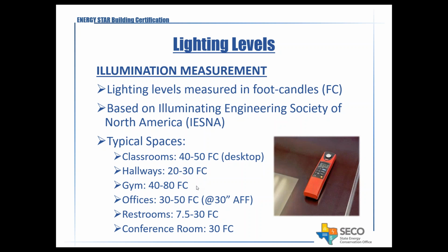Just note that UIL gyms in high schools will actually have a higher recommended foot candle level than, say, an elementary school gym. For offices, they're looking for 30 to 50 foot candles, and that's typically measured about 30 inches above the floor. And then restrooms, conference rooms. Different space types will have different recommended lighting levels, and that's what we're really looking for during the site visit. So typically we will spot check a couple of areas and make sure that it's meeting the illumination levels.